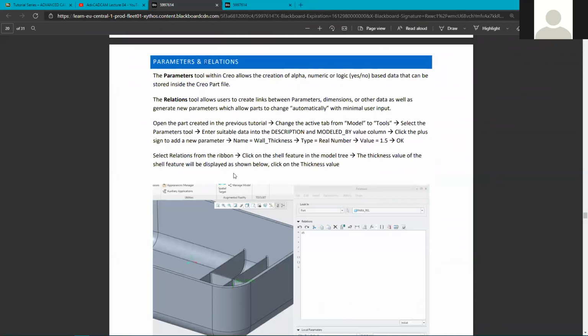So we have our box design. We've put a lot of static values into there. So we've manually entered things like thicknesses and dimensions of our rib feature as well. We put a lot of dimensions into that first rib feature. So those are what I'd consider static values. They're user entered values. But what you want to do sometimes is calculate certain values using other values in your design as a starting point, and then maybe apply a little equation to that original value to generate your other value. And this is a good description of what you can do with the relations